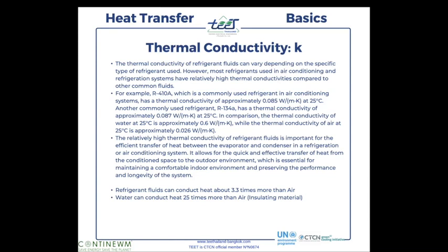It does not matter, if you use Continuum, you will still make the same savings because we are not working inside of the machine. You remember what I said? The evaporator coil, you have two heat transfers. One is from the air to the outer part of the coil, and the second one is from the coil to what is inside the coil, the refrigerant fluid or the water. So you can work to improve what is happening inside the coil. We work on what is happening outside of the coil, basically. So you can accumulate the savings. Did I answer your question?